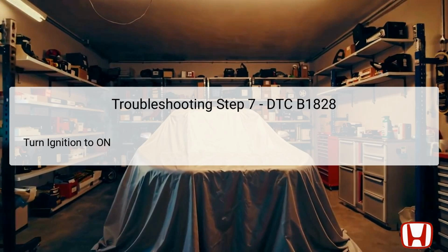Reverting to the on position supplies power to the control unit and all seat adjustment components crucial for the functionality verification of the recline motor. Properly executing this step provides a clean slate for electrical signals, enabling any further tests to reflect the true condition of the seat mechanisms. It's vital to ensure that the ignition switch is functioning properly to avoid additional complications when assessing the recline motor